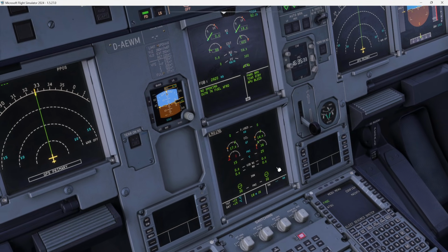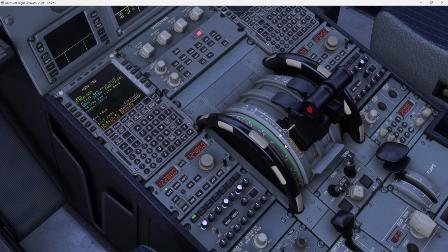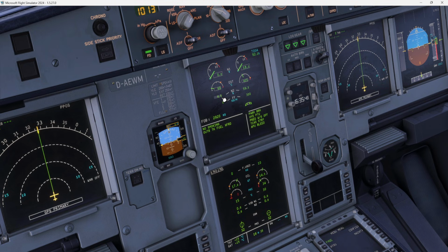Now we need to wait. Okay, we need to wait to see if everything is stabilized. Well, generally the FADEC is going to take control, but here we have a good startup and we had the engine available. Let's go to engine number 1, correction. N2 is rising.